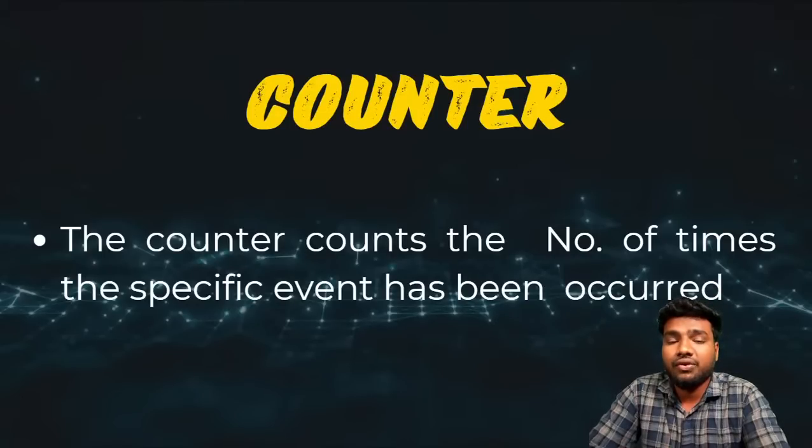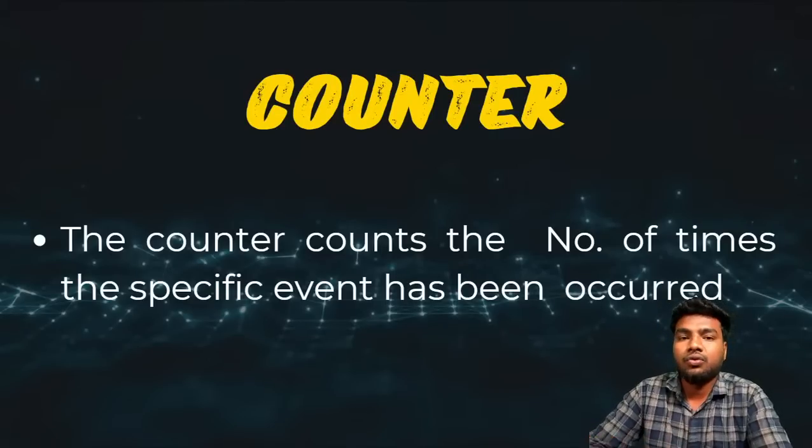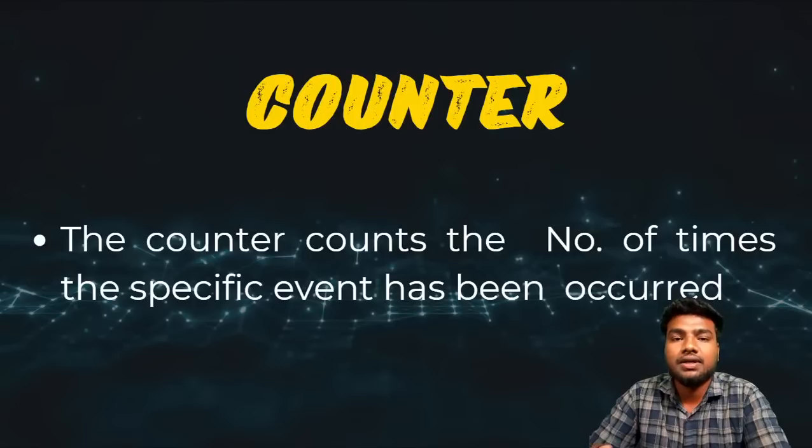Mostly we use a PLL in the tool. If you take Xilinx or Altera, there is a PLL block. By using the PLL, the tool will write the RTL code for the frequency divider. If you want to do it manually, you have to use counters.